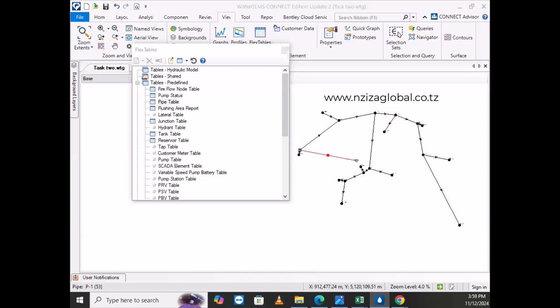The pump cannot operate 24 hours, continuously pumping. At least size it so it will have 4 or more hours to rest. So let's take 12 hours for us. Most of the time, the recommended values are 6, 8, 12, 16, and I think 18 also. Maximum is 20.